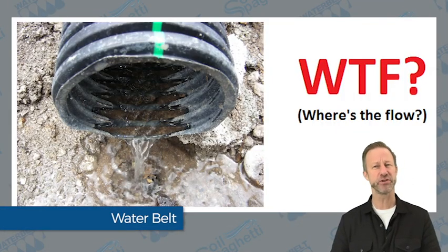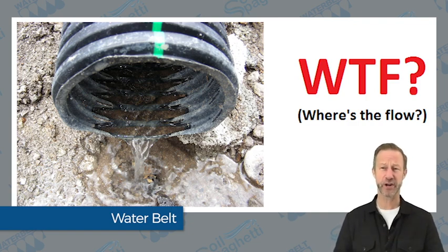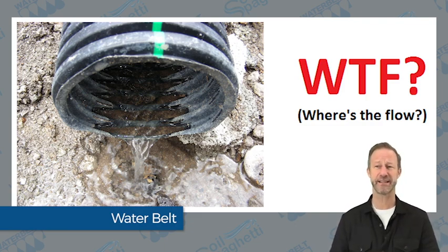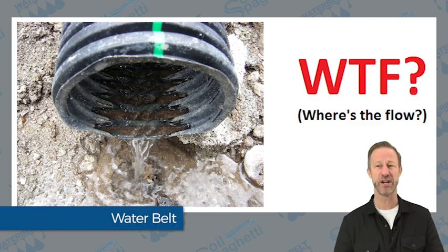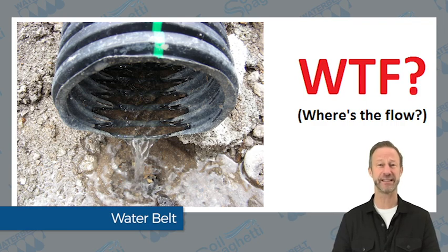Generally speaking, most drainage system problems originate from using components which were not designed for the purpose. Pipes were designed to transport water and do a perfect job for this function. They were not designed to collect water and as a result do a less than adequate job when tasked with this function. Although the discharge rate for a pipe this size is approximately a 5-gallon pail per second, it has no bearing on the drainage capacity since the flow is limited by the amount of water it can collect.